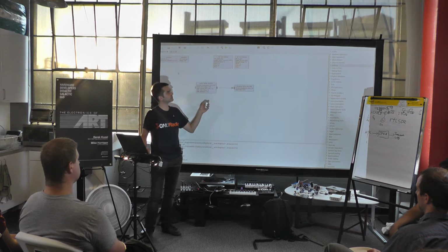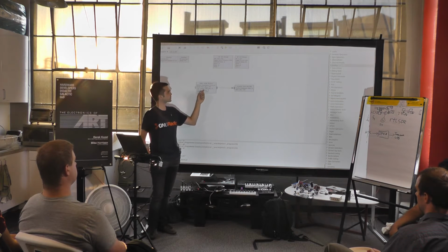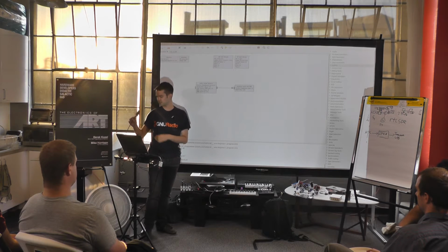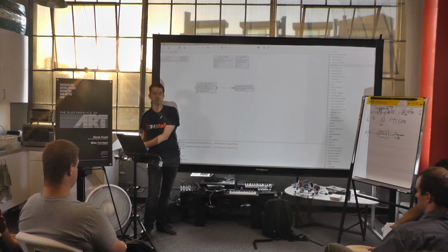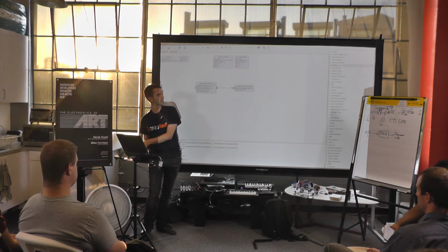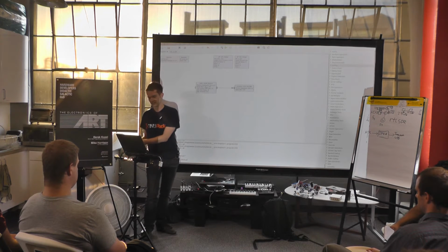And so this is GNU Radio. This is the same toolkit that was used to build the software that I was just running. And what we have here is a USRP Source. So that's this radio that I have attached right here, just a small board, but it's able to receive much wider signals. Signals, in fact, that are 30 times wider. So up to 60 megahertz of simultaneous spectrum. And it can tune anywhere from 70 megahertz up to 6 gigahertz, which gives us quite the ability to look at different signals.